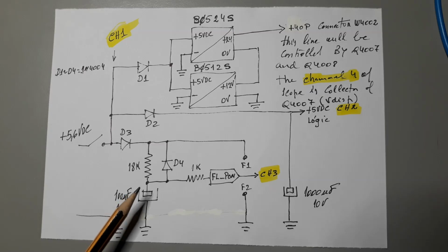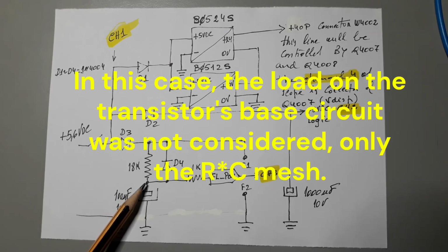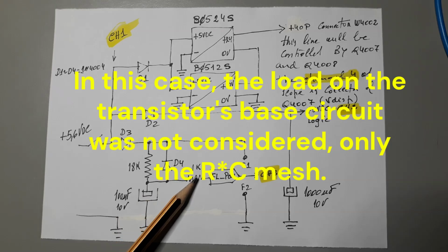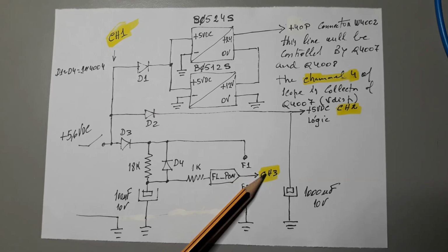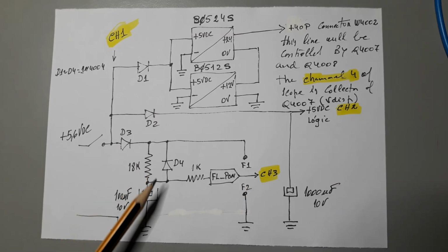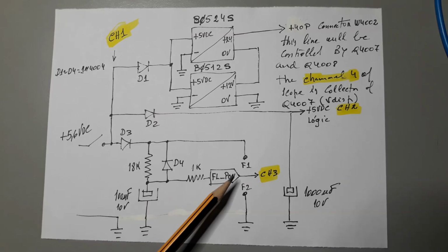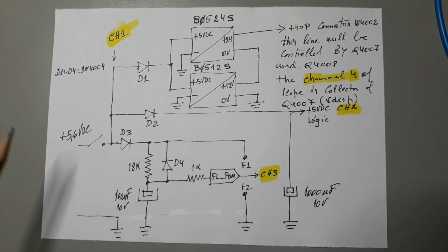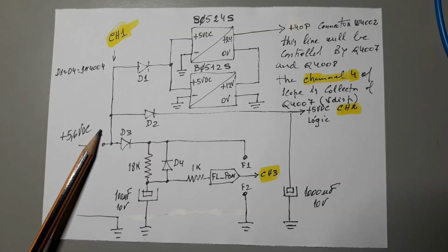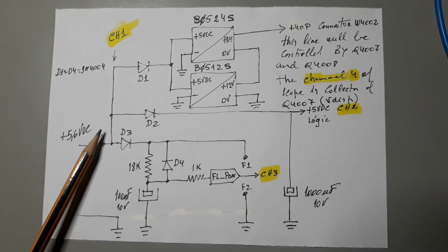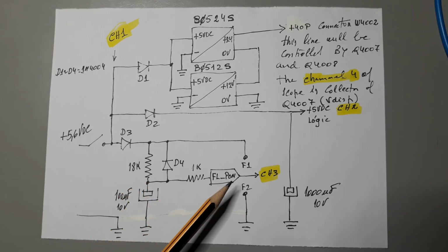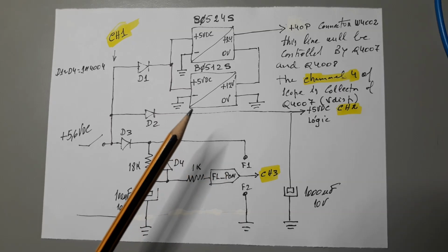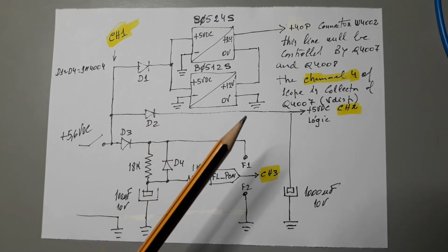After you load or after you reach the voltage of the first tau, the polarization of the transistor which controls the switch of the voltage to the grids and segments will be on, okay? It takes a little time to load and then activate the switch. This means after you apply here the plus 5.6 volts, only after some time the switch will be activated to switch on the voltage on the grids and segments.